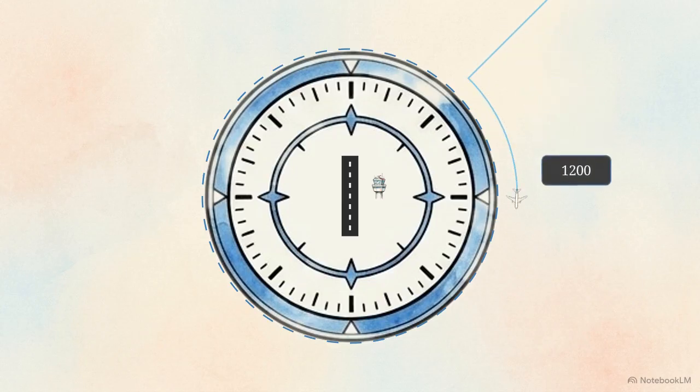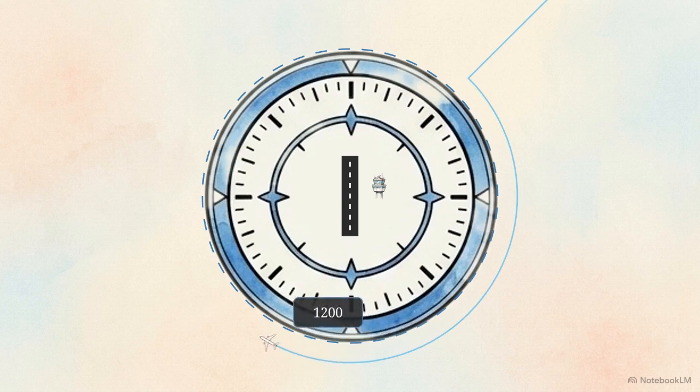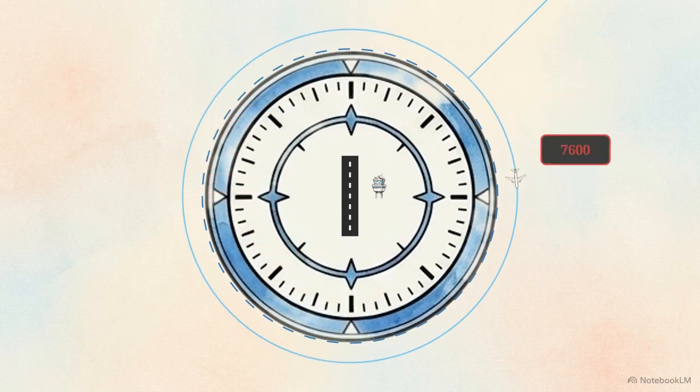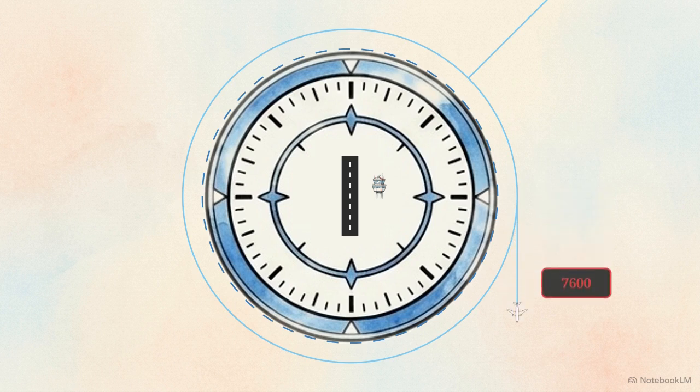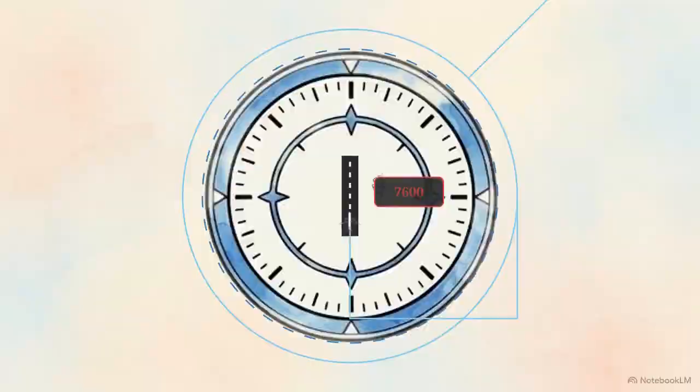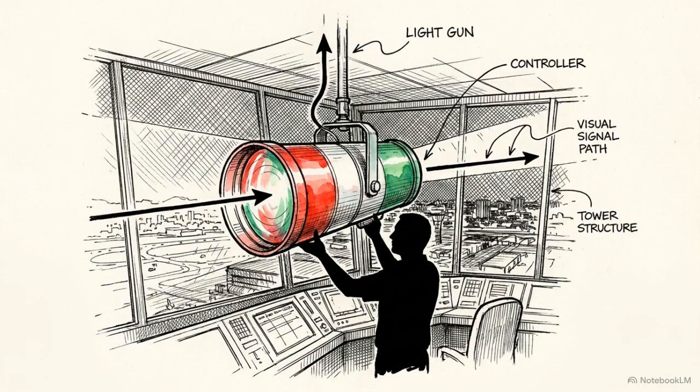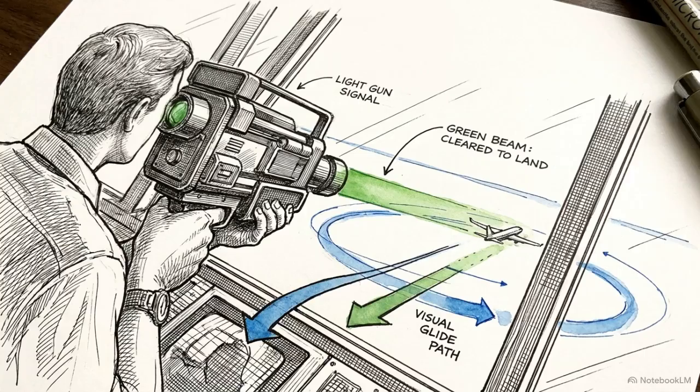Consider an aircraft approaching a highly congested, controlled airport at night when the radios suddenly die. Total communication failure. The pilot instantly initiates the mandatory lost comms procedure. They remain outside the controlled airspace, dial the emergency code 7600 into their transponder to silently alert radar controllers of the failure, and maneuver to enter the visual traffic pattern.